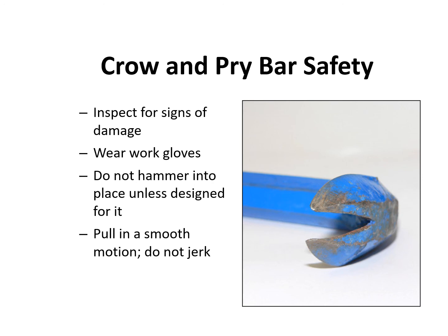Do not jerk the crowbar. Jerking may cause whatever you are prying to break or splinter, and you could go flying in the direction of your motion.